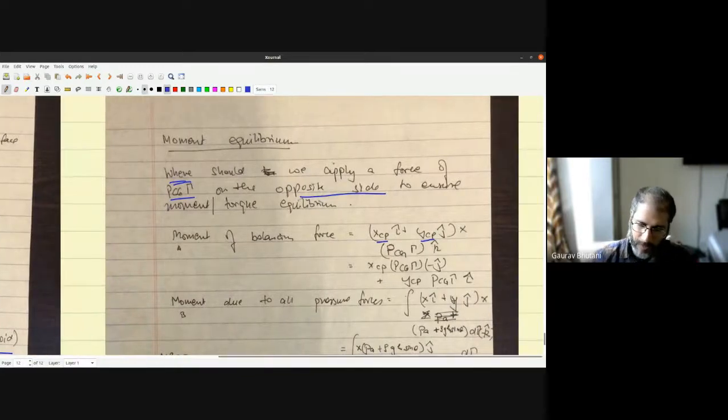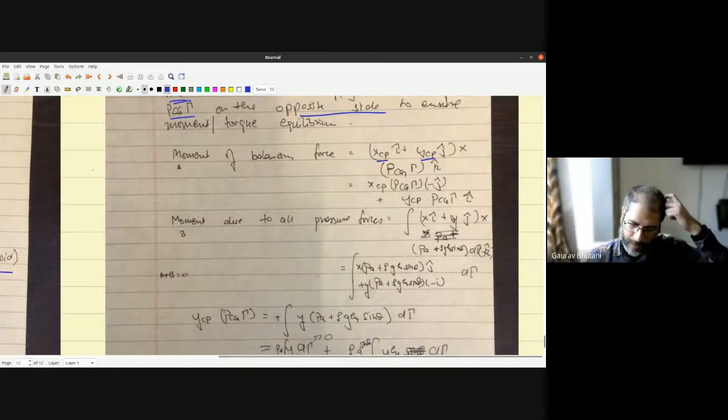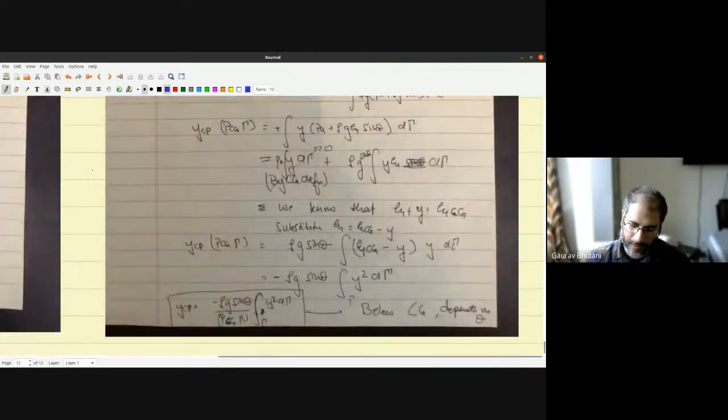So when you proceed with these steps to calculate, of course, you have to balance this with the overall pressure forces. Then you have to do an integration, and what you finally get are the coordinates xcp and ycp. You can do it yourself. There's nothing amazing here in terms of physics. And what we see here is that ycp is negative.